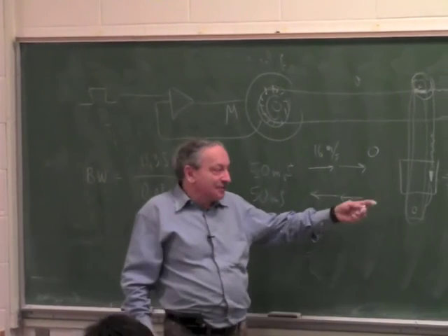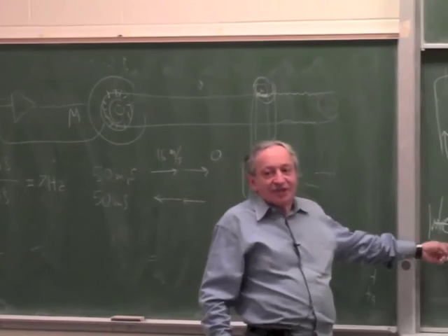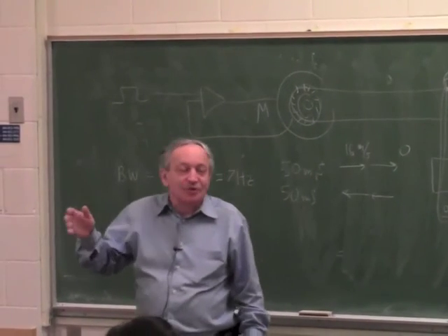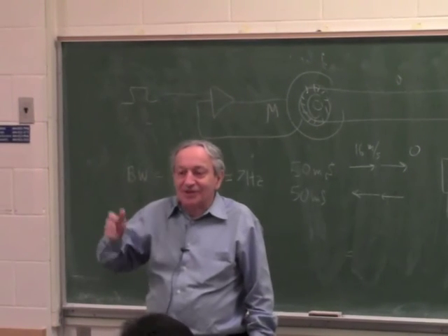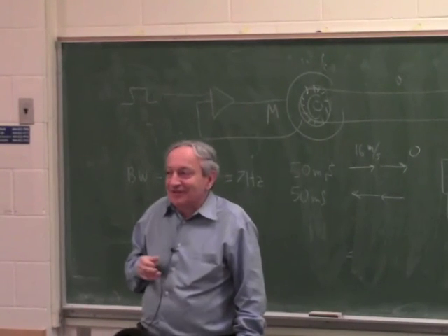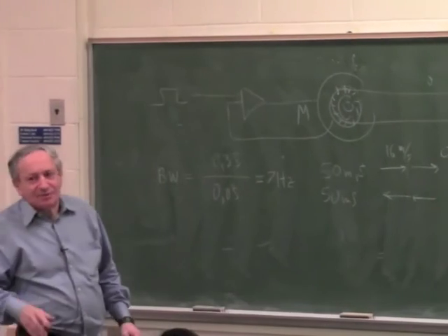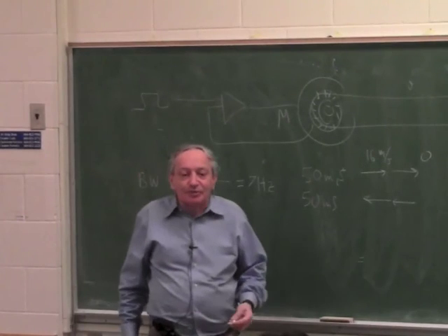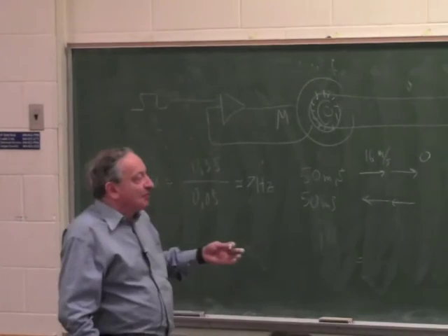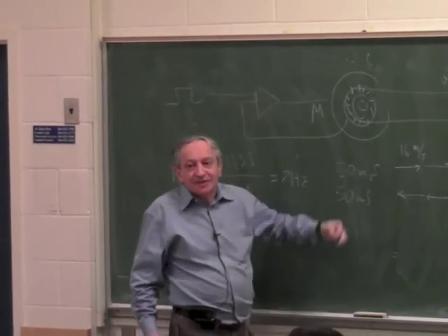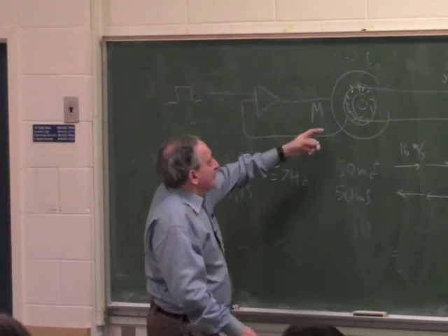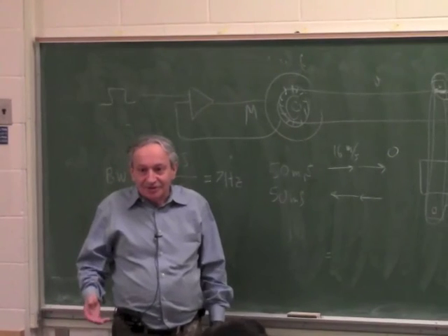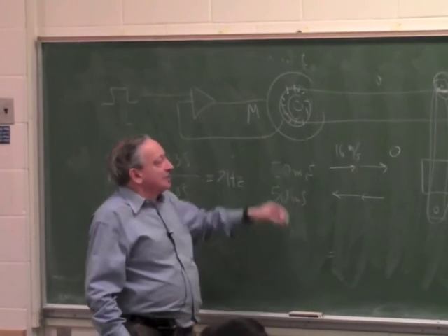So we're talking here about, even at 10% of the energy, hundreds of watts, right? Because without that, it was 2500 joule times 2.5, right? Was 6 kilowatt. Okay, but if I didn't make any mistake here, sounds a bit high, 6 kilowatt. But anyway, it was many watts. But even with regenerative braking, we're talking about hundreds of watts. So obviously it's not a stepper motor, which means we have to have some other motor, say an induction motor, okay, and then it means we have to have an encoder. Could be a DC motor as well, but still means you have to have an encoder. So in terms of sensor, a regular encoder is good enough.